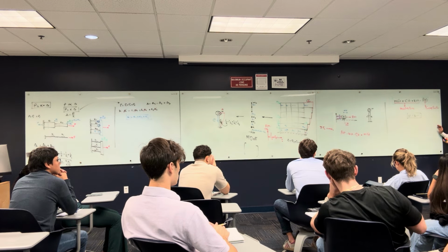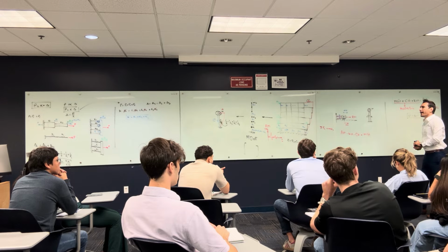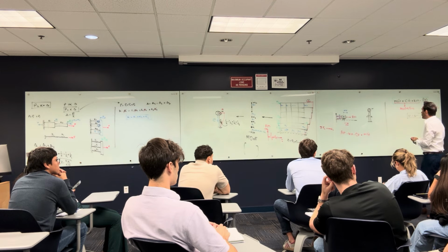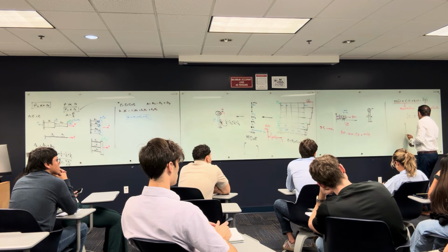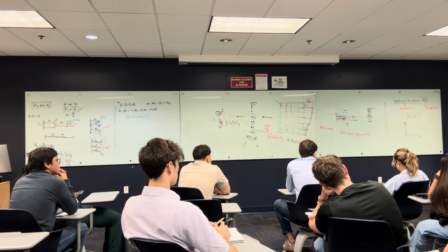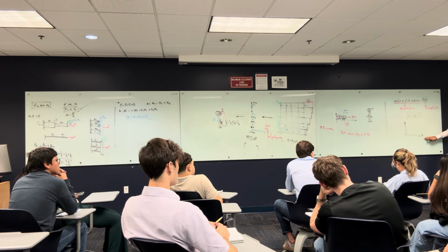So let's see what the codes do to solve the structures. As structural engineers, we don't want to get involved with too much math. I need one function, a curve. That's actually what we do in standards. This curve has a parameter about the building. It's called T, the fundamental period of the structure. I'm going to tell you what that is in a little bit.